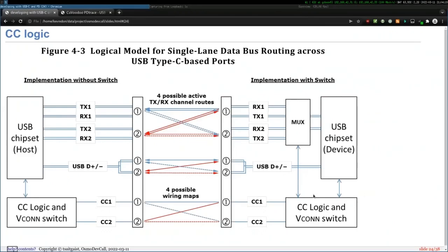I use the ROM from the Chromium OS. Chromium developed their own USB-C power delivery stack because they wanted to control the chip on it. They want to have all the firmwares open source on the chips, and I just reuse their stack. So this is open source, and because I only compile what I need, it shrinks the size of this binary blob a lot.